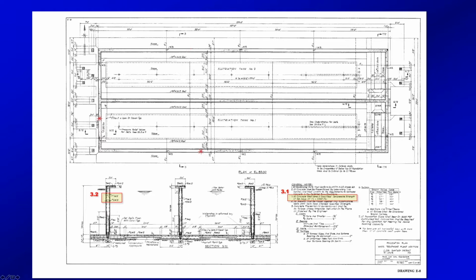Okay. So if I'm doing that, obviously they got a section here, 3-11. So I'm looking at 3 and 3. I have no idea why they call it 3-11, but they call it 3-11. So basically speaking, I'm looking into the wall toward the right-hand side. So that puts this thing here up there and this one here right here. Okay. So those have to be the outside walls. So I just go look at the typical reinforcement for all the outside walls, 7-12 and 6-12, and then the inside wall, 7-12 and then 5-12. So they just made the bars going horizontally one bar size smaller. I'd be very confident that that would be the answer.